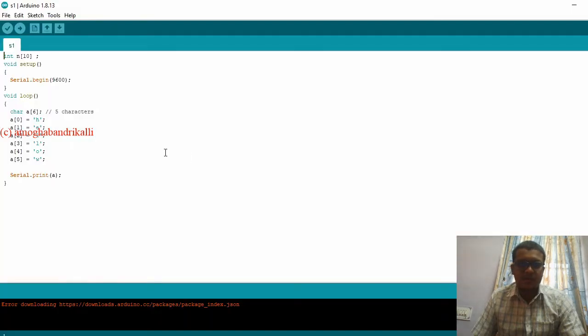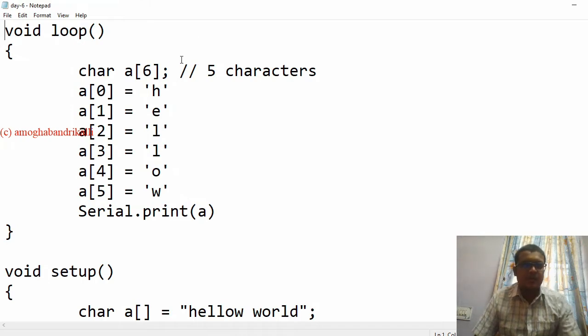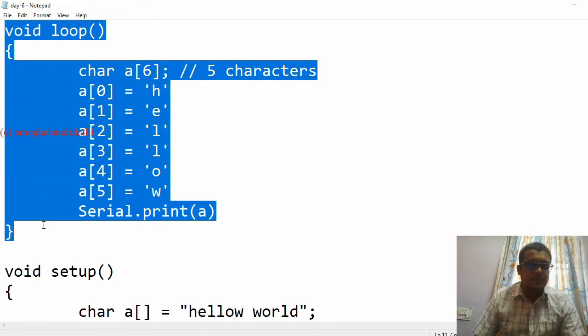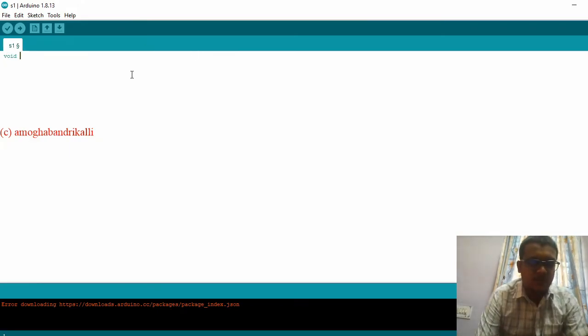So we have an Arduino here, and we have the array classes that we have just done. Okay, we are going for typing void setup. Inside the void setup, after writing void setup, you can have two curly brackets and one tab. So you can have Serial.begin, and I am using a baud rate of 9600.